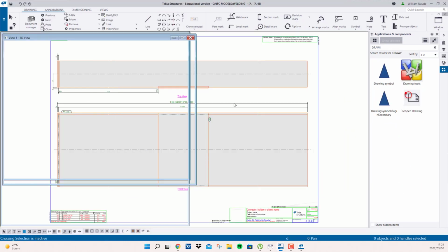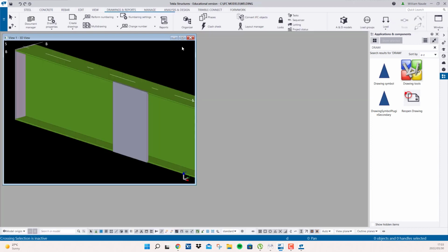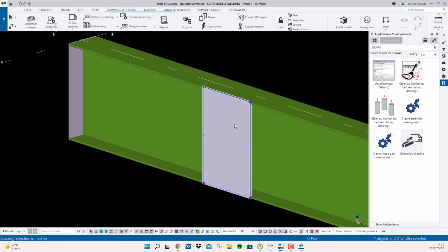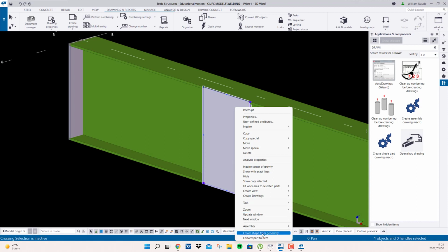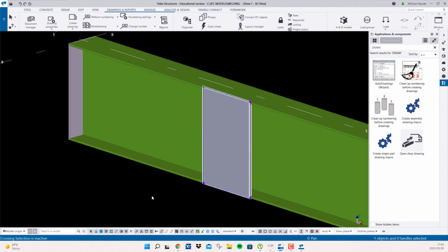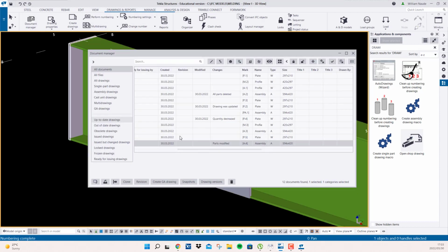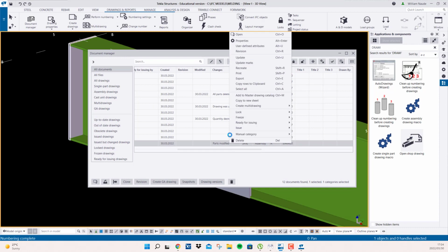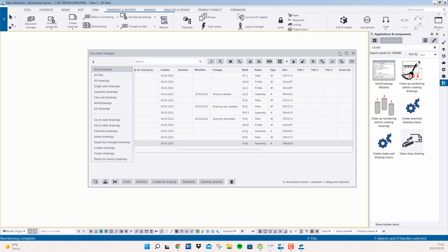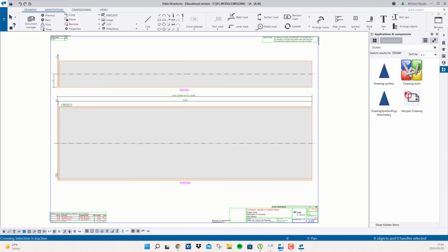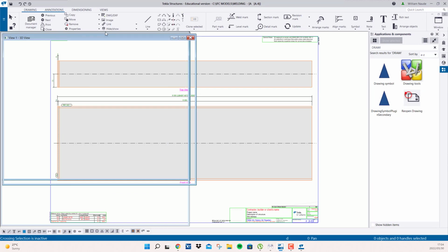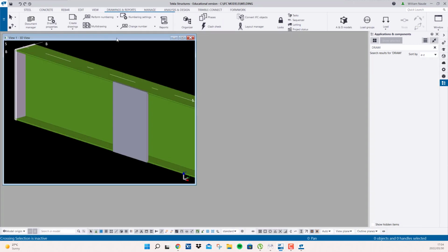To remove this, you have to say again, remove the item from your assembly, because you can't delete it, because it didn't have a weld. So you can then choose assembly and say remove from assembly. And once you've done that, and again, you perform the numbering, the part will be modified. And if you open it up, you'll only have the one plate on the left-hand side. So this is one way of creating an assembly drawing as well.